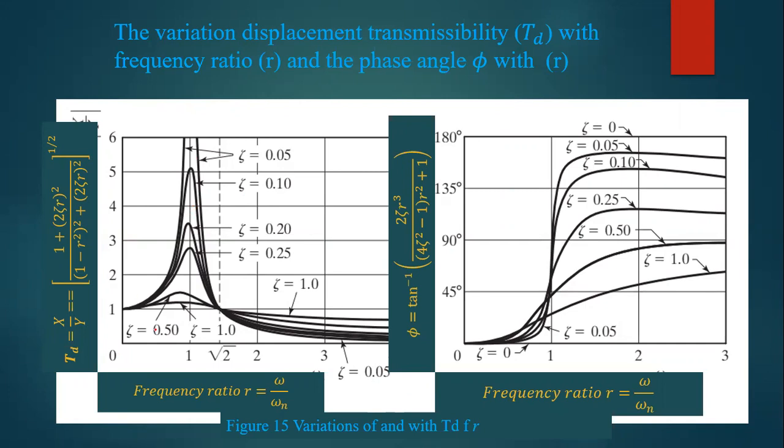Okay, so for various damping factors, we can find various plots here. For very little damping, it goes to resonance. Here, what we are looking at is near the resonance point, where omega over omega n is equal to 1, meaning resonance. If there is no damping, it will go to resonance. So for very little damping, we can see high overshoots.